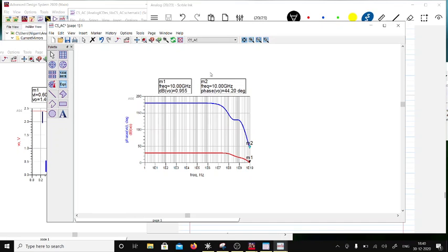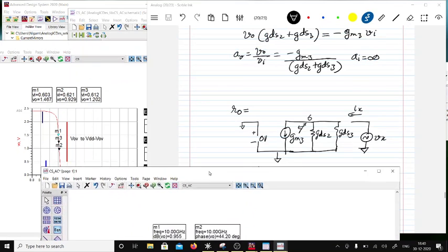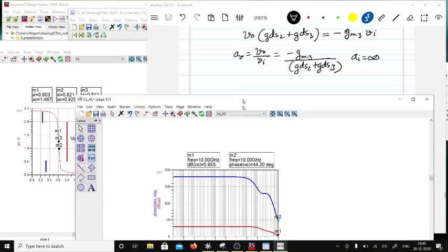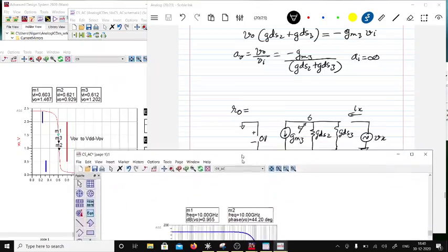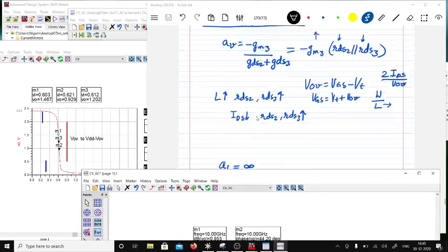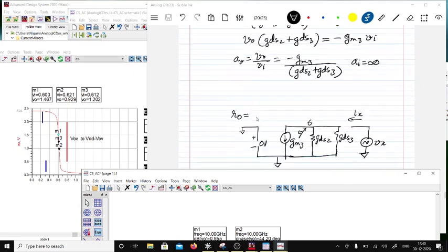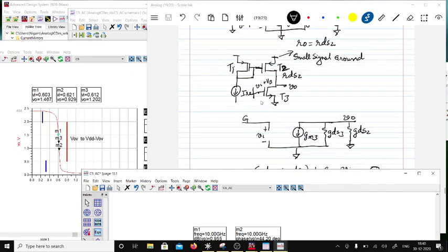Now why am I considering 180 degree roll off? Because if you see this transistor, this transistor has a 180 degree phase shift. And now if you have an additional 180 degree phase shift, then whatever is that voltage will cause a feedback to the input which is 360 degrees. This is known as the Barkhausen criteria. So what is the Barkhausen criteria?